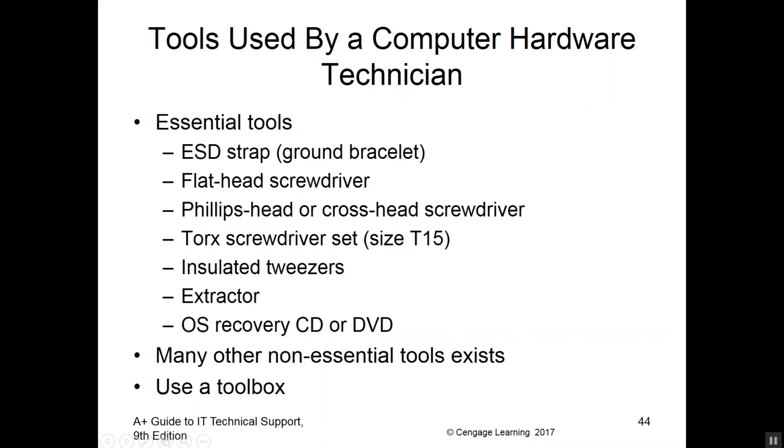All right, so we've got essential tools. We've got the ESD strap or grounding bracelet. Like I said, ESD, that's electrostatic discharge, or that shock from static electricity. Now, that's not to protect you. That's to protect the device itself from the charge you would emit.